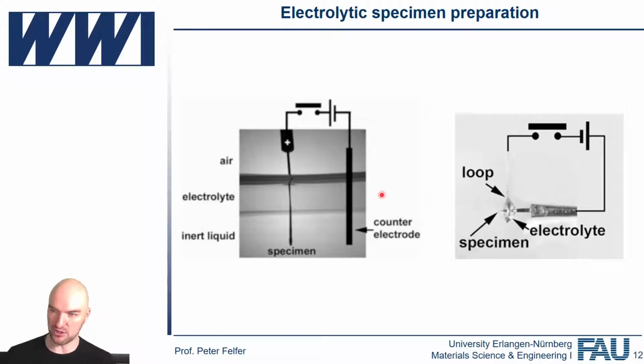If you imagine you just do that in a chemical polishing agent, it would just keep polishing once you already have your atomically sharp tip, and it would make it blunter and blunter. So we're using electropolishing, at least for the most part. Sometimes chemical polishing is actually used, but it's relatively rare.